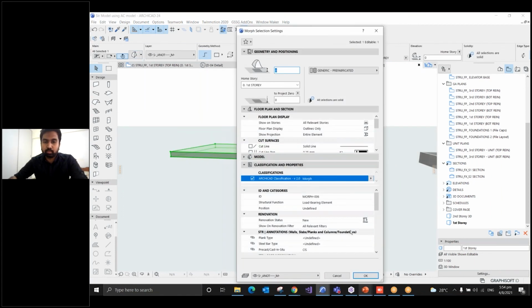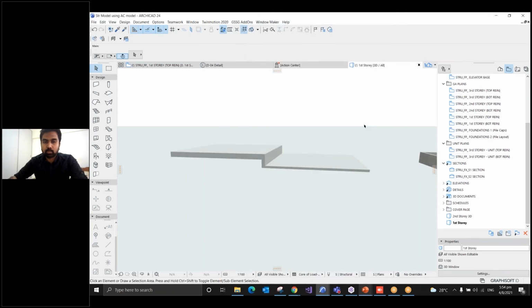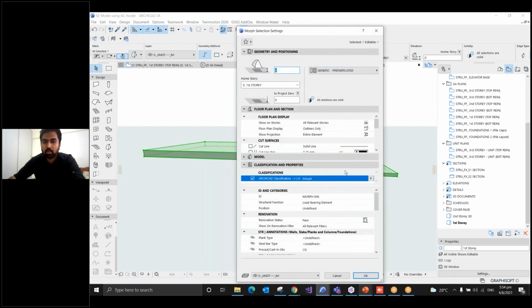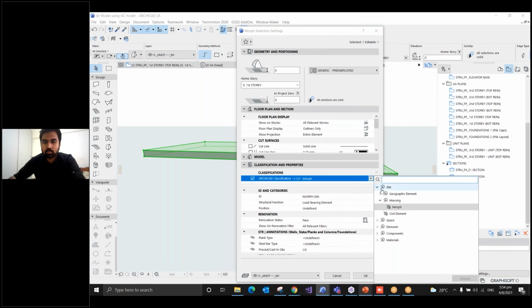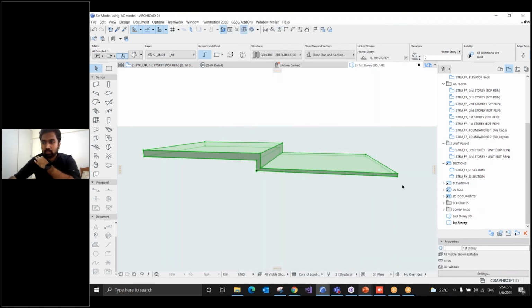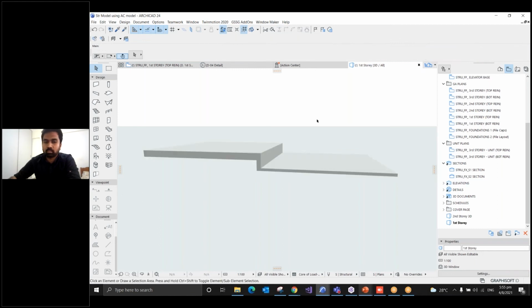For example, it drops. Sometimes if you use a morph and you do a composite slab, there are a lot of things you have to move, isn't it? Is that the right way to do it? Okay, for a composite slab, you have the finishes separately. Here it is a structural model, so we are focusing on the concrete part only, right? So you won't have the finishes.